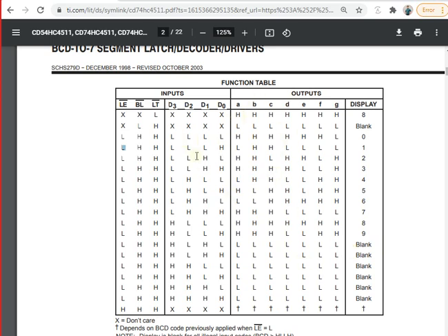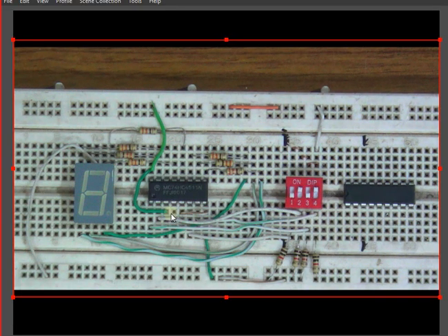Oh, the conversation. So over here, these three are just fixed inputs, just like over here. So third and fourth, you can't actually see the jumper wire. I have placed a jumper wire just below this one. So third and fourth, I have combined them together over here, and then through a jumper wire, I have taken them to VCC. So third, fourth pin have been given 5 volts, and the fifth pin you can see from here to here where the mouse is hovering. This is the ground connection, and from here the ground connection is done over there.